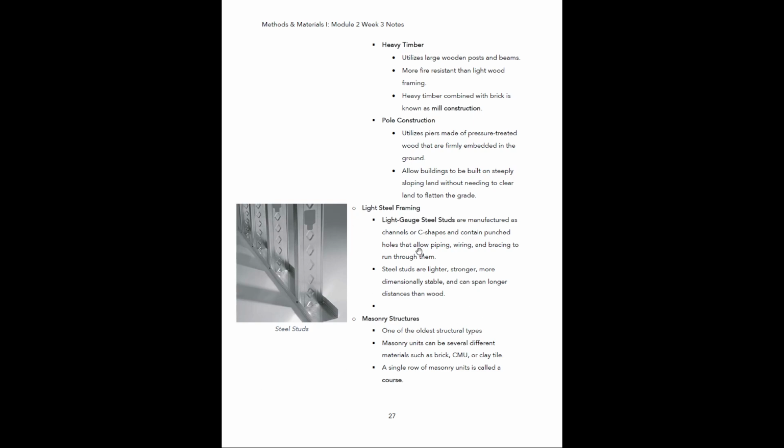You have to take these things into consideration, because you put something together one day and it looks good, but over time it'll contract or expand, and that will change the way it's being held together. So if you have a wood floor that's subjected to a lot of temperature changes over time, that shrinking and expanding can cause the nails in the floor to come loose. So if you're in an old house, for example, and the floors creak, that's why.